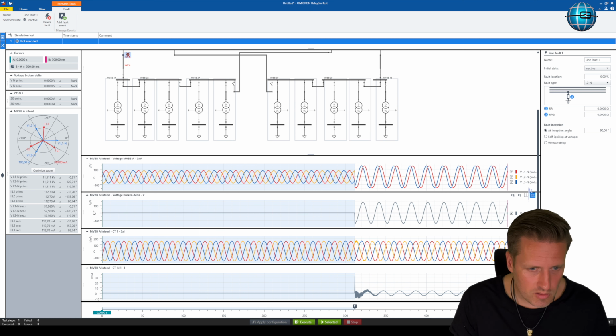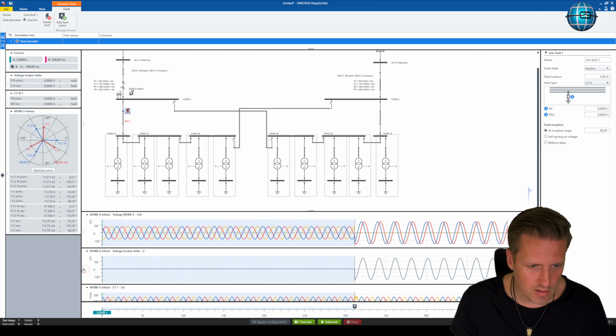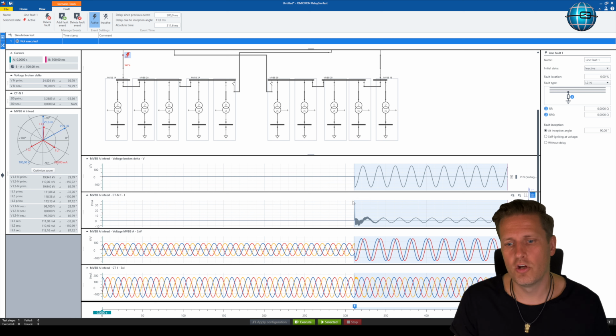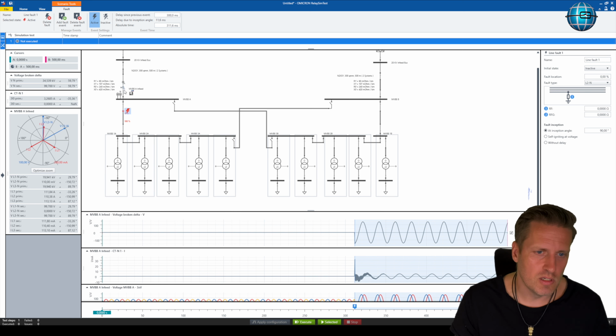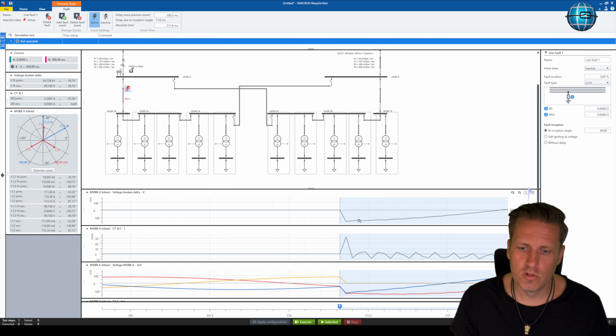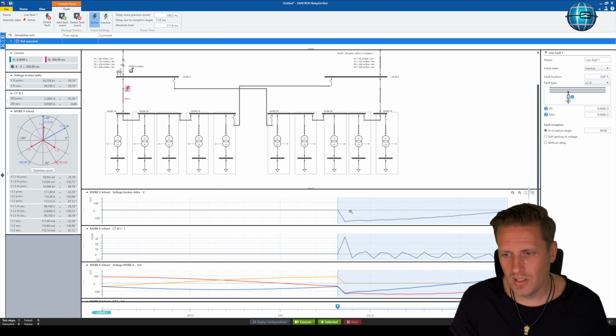We have here the voltage of the broken delta. Let's put this to the top, and we have here the current transformer, which is the split core transformer, which is sitting here in our in-feed. Okay, and now we want to see this first moment when the earth fault occurs, and what we can see here is that the voltage amplitude is negative and the current amplitude is positive.